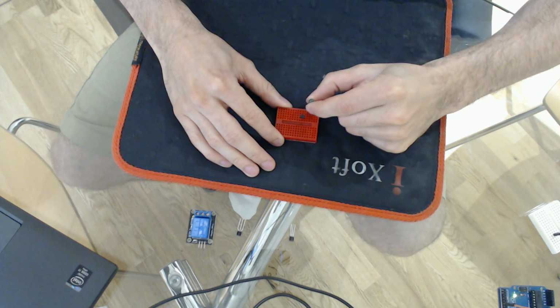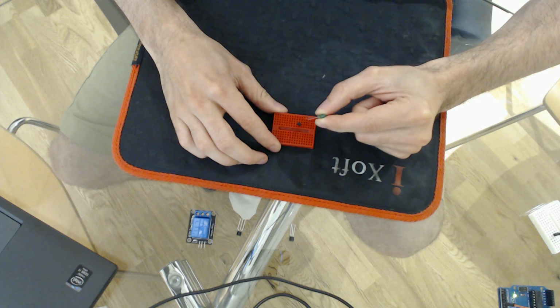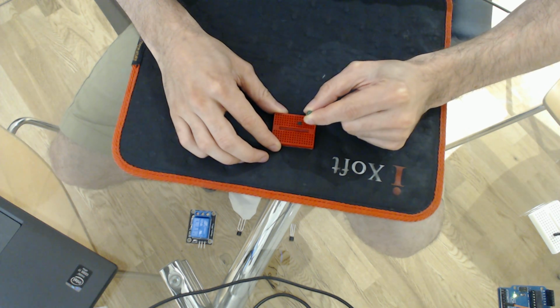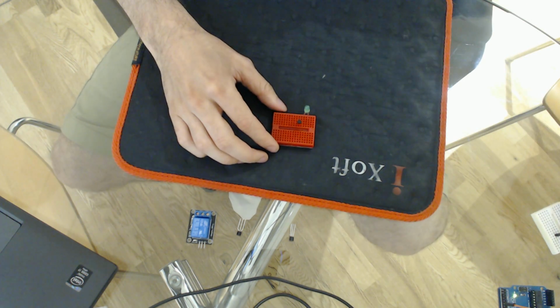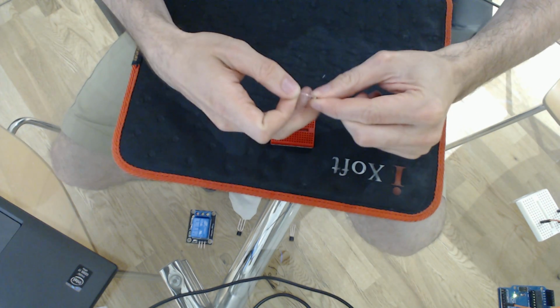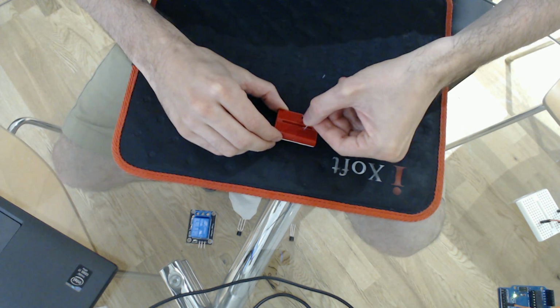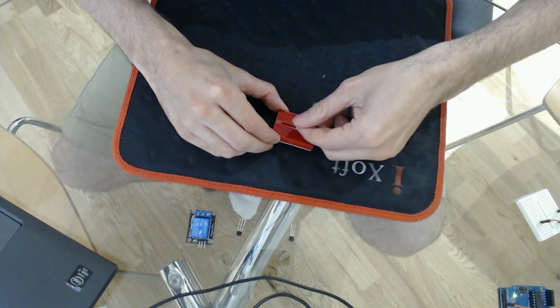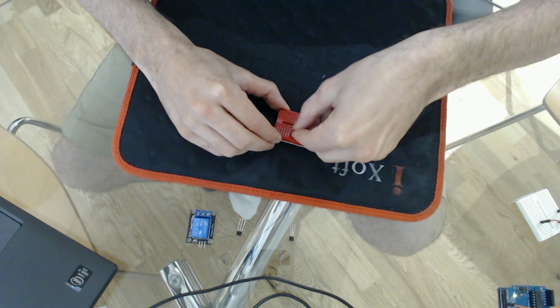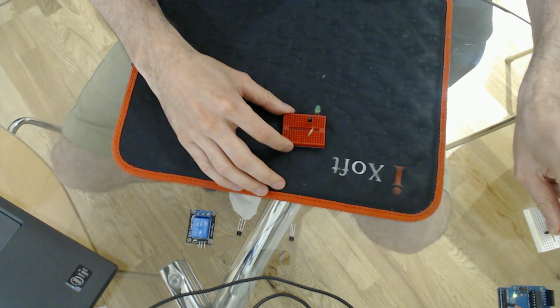So the LED here is going to have the ground pin on the collector and the positive a little bit far. We're going to use a resistor between the base and the digital output of my Arduino to avoid any discharge going through my Arduino so it will not damage it.